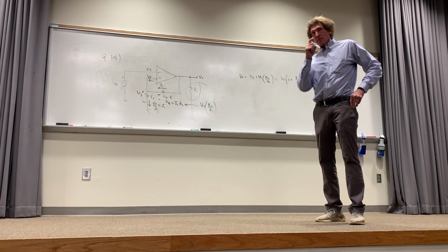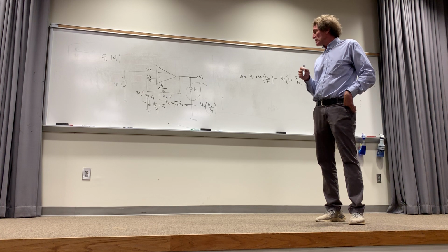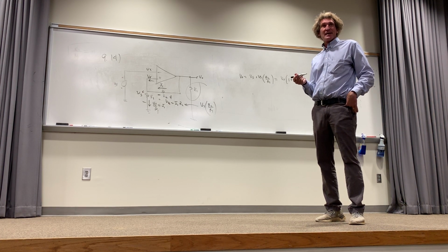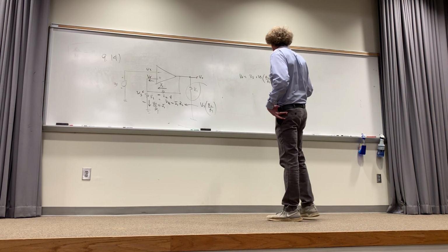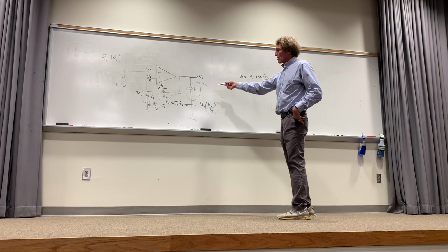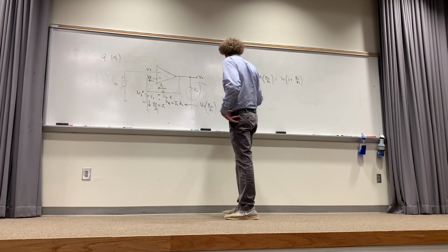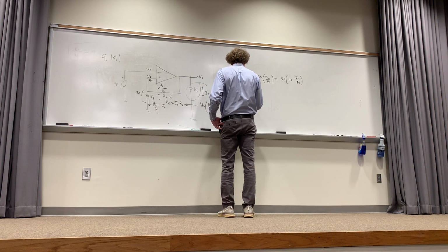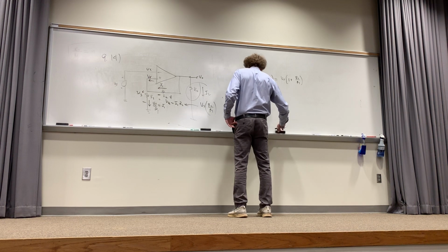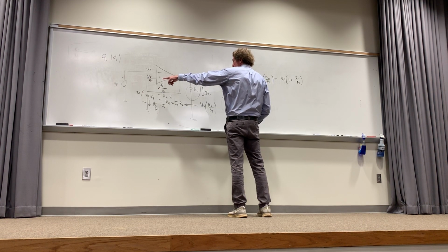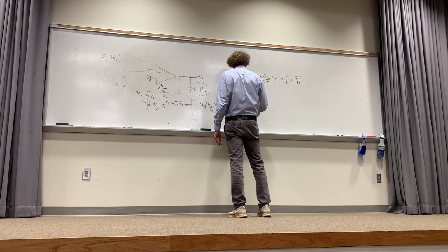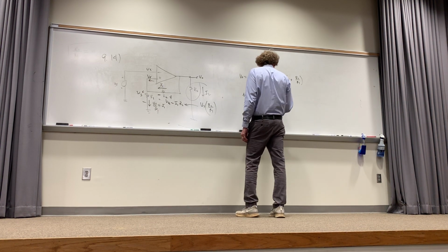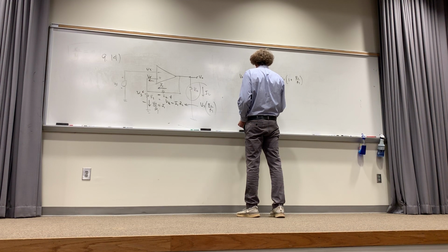Yes, for B, what is the maximum current through RL, and then for C is the maximum current output of the outlet. Well, the maximum current is just going to be the voltage V out right here, divided by whatever this is, RL, right? So if I want I this way, IL, I think this is a time domain. Does he have a voltage source that's like a cosine or something? Yes. All right, well, then IL in the time domain of t is just going to be V out over RL.